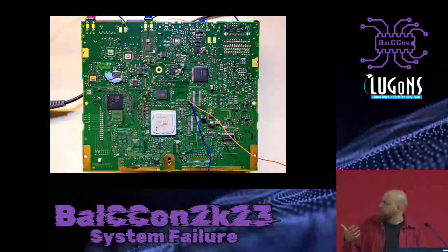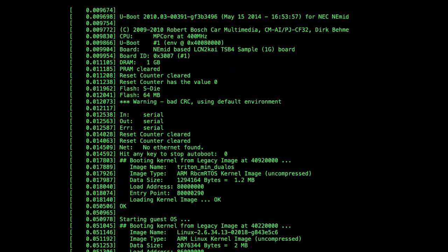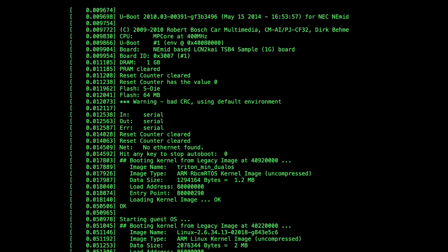In this picture, an interesting thing is these two wires that are coming off of it. Those are TX and RX lines for a serial console. With some tracing, it was relatively easy to spot that there's a serial console somewhere there, and I broke out these two lines so I'd be able to communicate with the device over serial. Which was all nice and dandy, but the console was locked. You can connect to it and see some messages, but you don't get shell access.